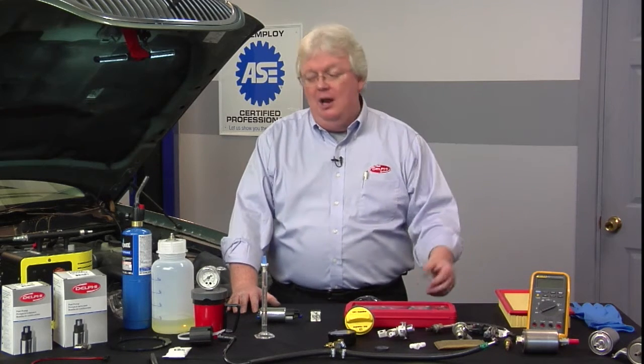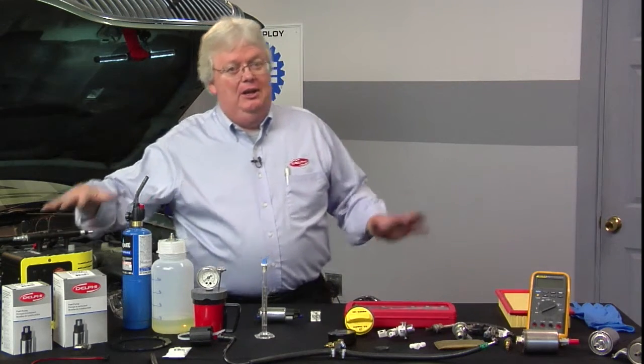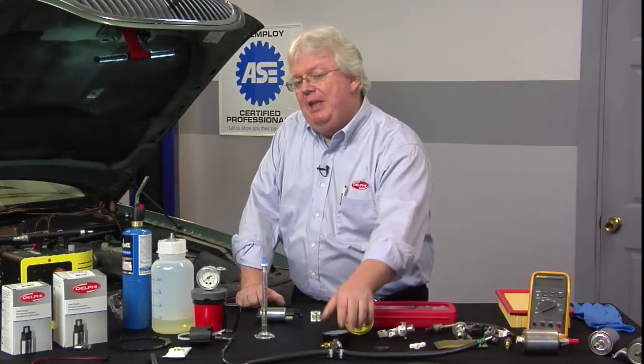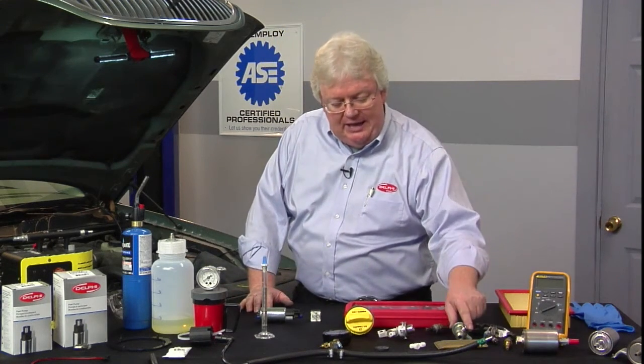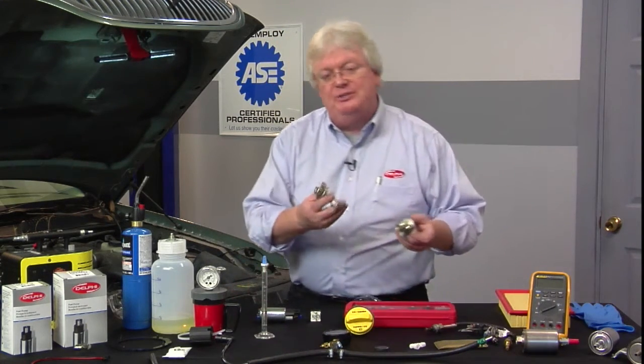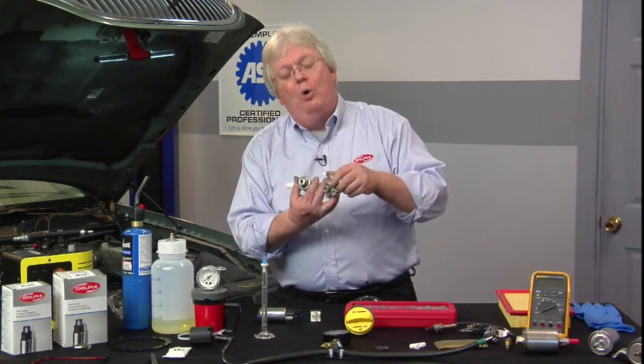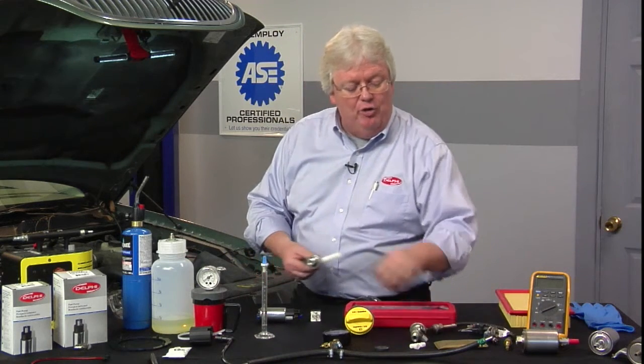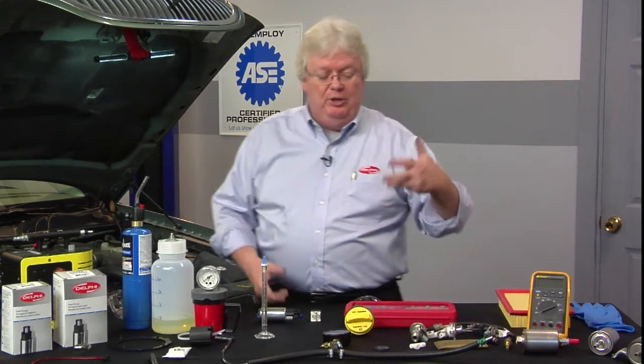So what will we do there? Well, we don't really need to use a smoke machine because the rich mixture is going to be too much fuel pressure. So that's one of the first things we'll look at. It could be a fuel pressure regulator, either in the tank, if it's a modular assembly with a returnless system, or the older systems that had the return system in the rail with the pressure regulator on the rail. That would cause it to be overly rich.